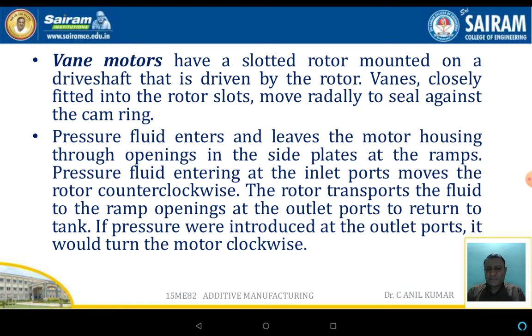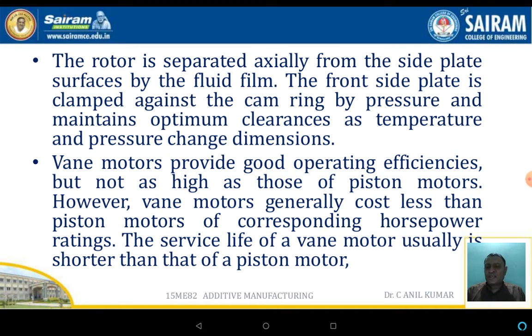If the pressure were introduced at the outlet port, it would turn the motor clockwise. The direction of the rotor depends upon the flow of the liquid. The rotor is separated axially from the side plate surface by a fluid film. The front side plate is clamped against the cam ring by pressure and maintains optimum clearance as the temperature as well as the pressure changes the dimensions.